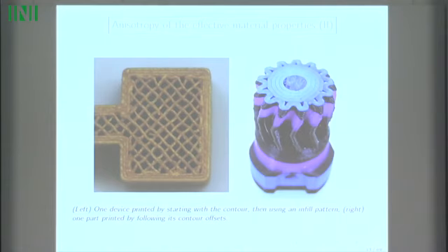So here is another construction pattern where the nozzle would make a concentric pattern starting from the boundary of the layer to the inside of the layer. So there is a need to model this anisotropic behavior and to incorporate it into the optimal design process.